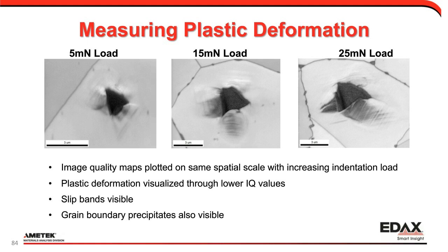You can see some slip bands that have been induced. So by knowing the orientation, we can pick a grain, but we can also rotate a grain on the surface. We can think about positioning things relative to the slip system, kind of applying force relative to the slip system to be able to see how material will respond